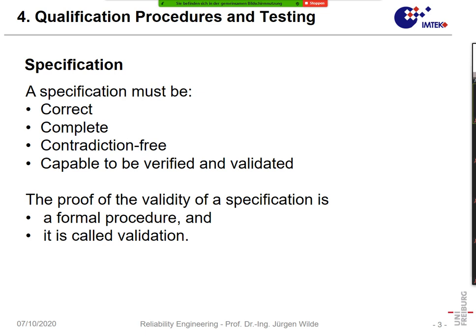In the end, they assembled it all, sold it to the customer, and a few months later, all of the customers came and said, "Oh, our machinery is broken, it doesn't work anymore." And in the end, what was the cause of these failures? The company had forgotten to specify vibration as an important property. So you can imagine if such a diamond blade cuts through concrete at high speed, there are huge vibrations.